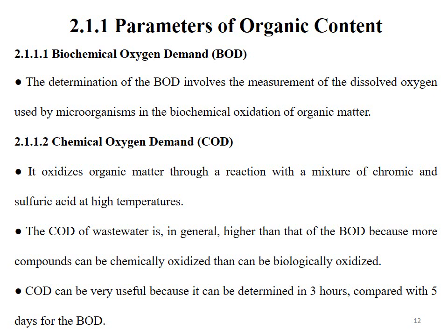Some important parameters related to organic contents are biological oxygen demand and chemical oxygen demand. The biological oxygen demand is abbreviated as BOD. The determination of the BOD involves the measurement of the dissolved oxygen used by microorganisms in the biochemical oxidation of organic matter, while the chemical oxygen demand, abbreviated as COD, oxidizes organic matter through a reaction with a mixture of chromic and sulfuric acid at high temperatures.